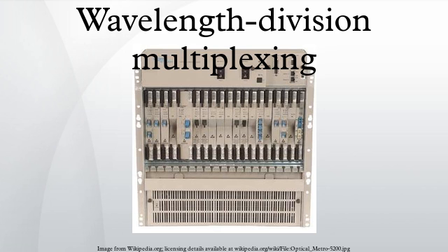Often, the functionality of the output transponder has been integrated into that of the input transponder, so that most commercial systems have transponders that support bidirectional interfaces on both their 1550 nm side and external side. Transponders in some systems supporting 40 GHz nominal operation may also perform forward error correction via digital wrapper technology, as described in the ITU-T G.709 standard.